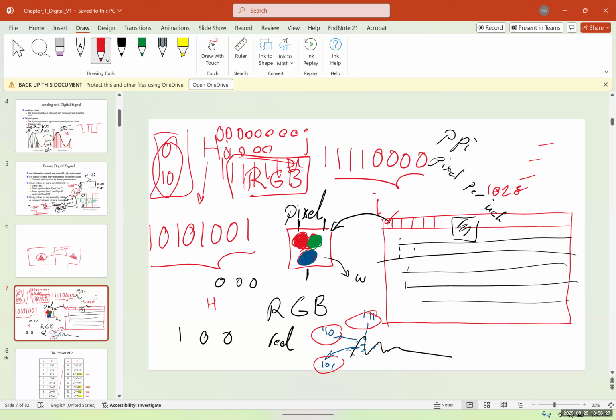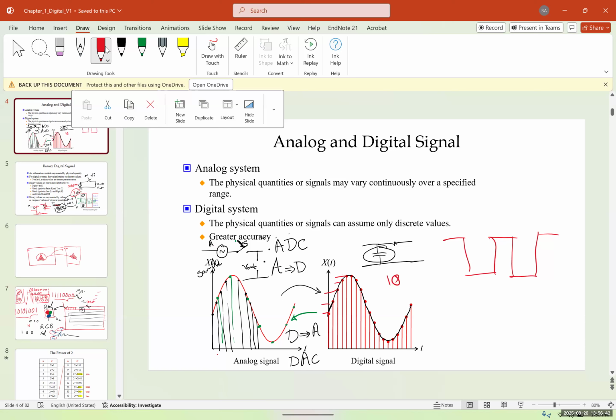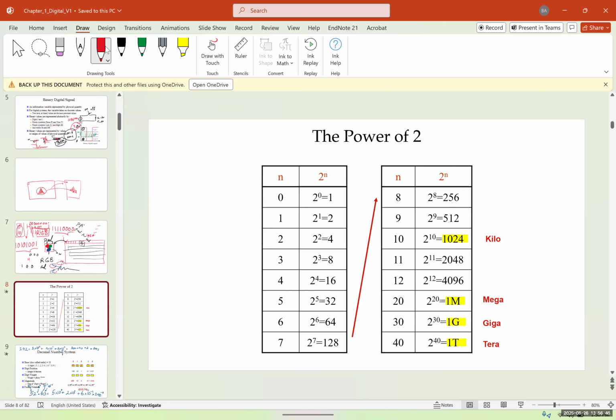And if I put, for example, 5 volts, I have 50% light intensity. If I put 0, I have 0%. If I have 10, I have 100%. Does it make sense? It was exactly like what we had here. Instead of having 2 levels, I have multiple levels in binary. And the more levels you have, the higher quality picture you're gonna have.